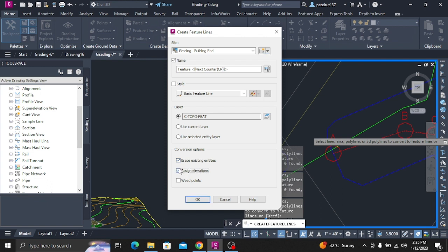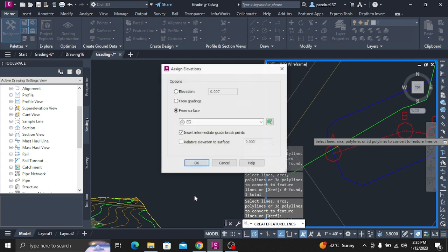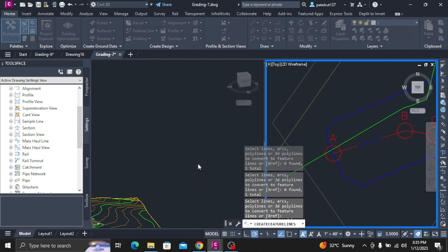In the Grading Elevation Editor, click Flatten Grade or Elevations. In the Flatten dialog box, select Constant Grade. Click OK. The grade flattens, and the elevations update to accommodate the new grade.